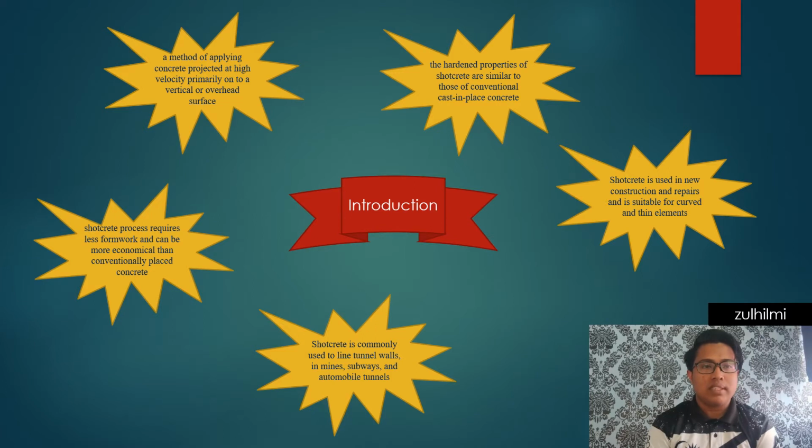The shotcrete process requires less formwork and can be more economical than conventionally placed concrete. Shotcrete is applied using a wet or dry mix process. The wet mix shotcrete process mixes all ingredients, including water, before introduction into the delivery hose. The dry mix shotcrete process adds water to the mix at the nozzle. Shotcrete is used in new construction and repair, and it is suitable for curved and thin elements.